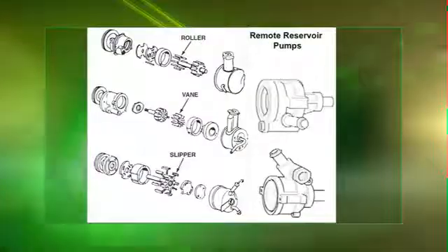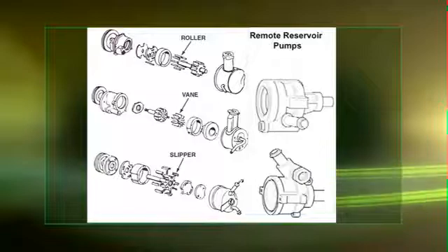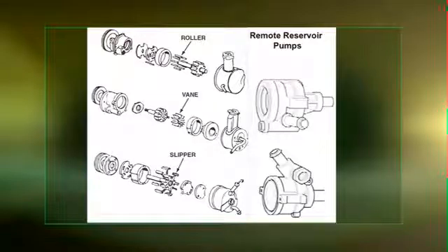Here are some power steering pumps you may run into, and how they look on the inside really is not of any matter in diagnosing them, whether they're roller or vane or the slipper style. This is basically a hydraulic pump. As the engine starts and a belt turns the pump, it's going to make pressure. The faster the engine turns, the higher the pressure it makes. At lower speeds, you may hear a squealing noise.